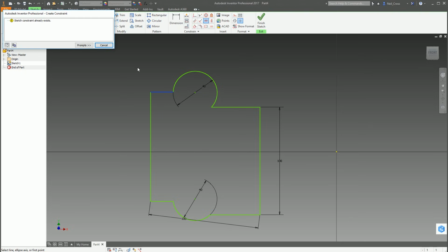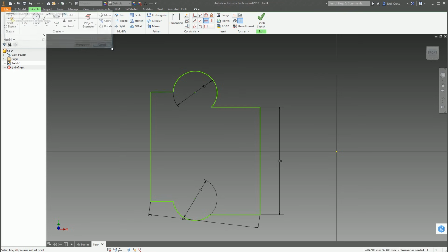see it gives you an error and it says, whoa, hang on a minute, you've just asked me to make the line horizontal. You've just clicked the line. You're asking me to make the line horizontal. It's already horizontal. The problem's not that the line isn't horizontal, it's that it's not horizontally aligned with this one. So you go, right, well then there's another way of doing this. You can say make the end point of that line horizontally aligned with the end point of that line. And then that brings them in line with each other.